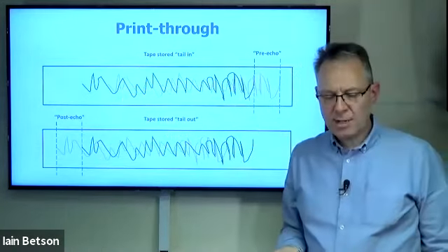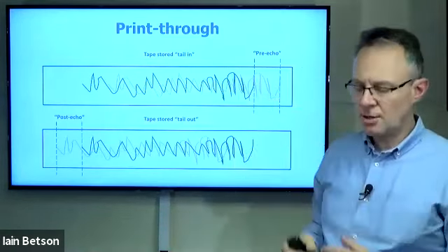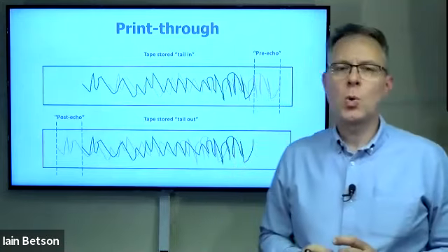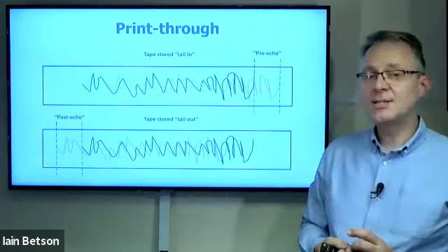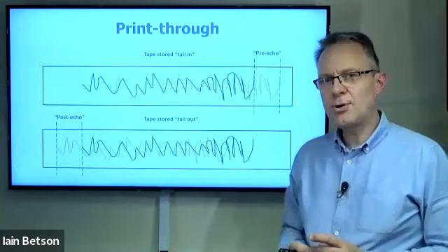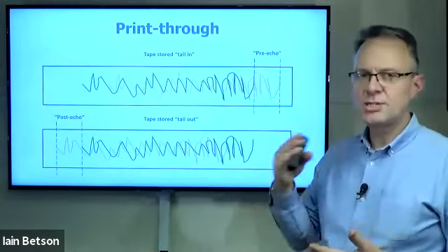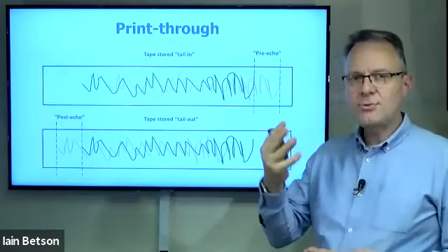Now, when I spoke about SM900, SM911 tapes and loud signal to noise ratios, when manufacturers talk about low noise tapes, you're more likely to suffer from print through from a low noise tape. And that's not because the action of a low noise tape is more susceptible to print through, it's because the lower noise is allowing you to hear the print through.